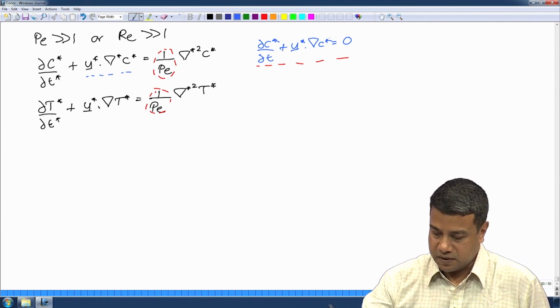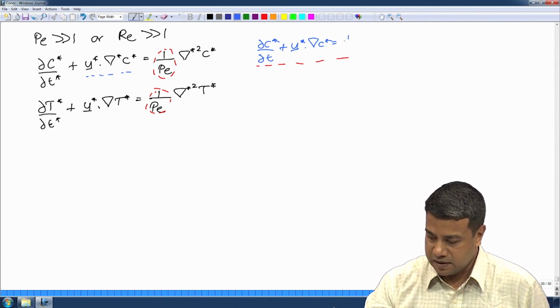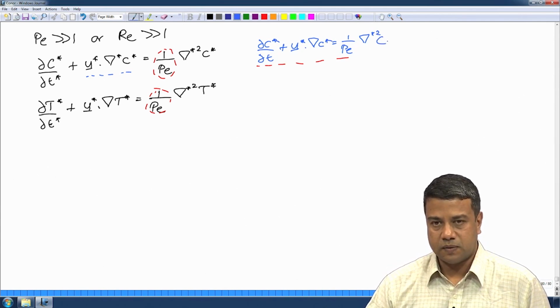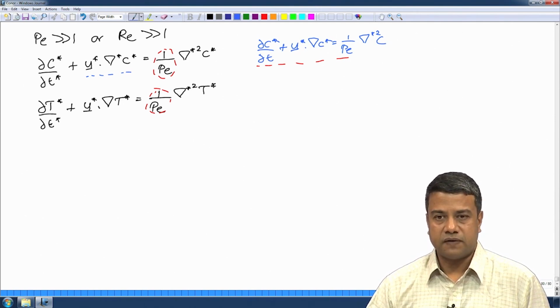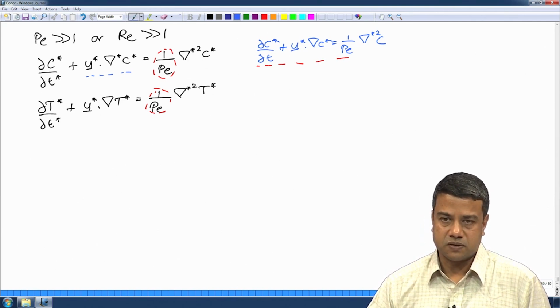So, what you need to do is to include the effect of diffusion very close to surfaces by rescaling the distance from the surface, within a boundary layer whose thickness is determined from the requirement that convection and diffusion have to be of equal magnitude within this boundary layer, even as the Peclet number goes to infinity and the boundary layer thickness goes to 0.